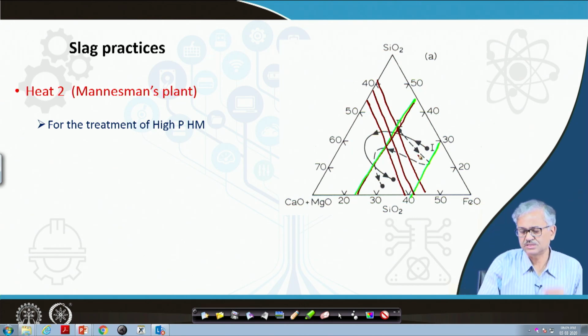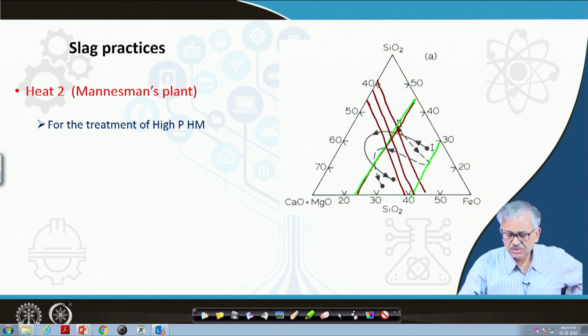Up to this point, we started with 25% FeO, then we did a soft blow, and I have developed FeO to a very high 40% without losing too much carbon. Then you can see the CaO starts dissolving and CaO is increasing in the slag. So, I have formed the basic slag in this condition, a significant basic slag is there, right.